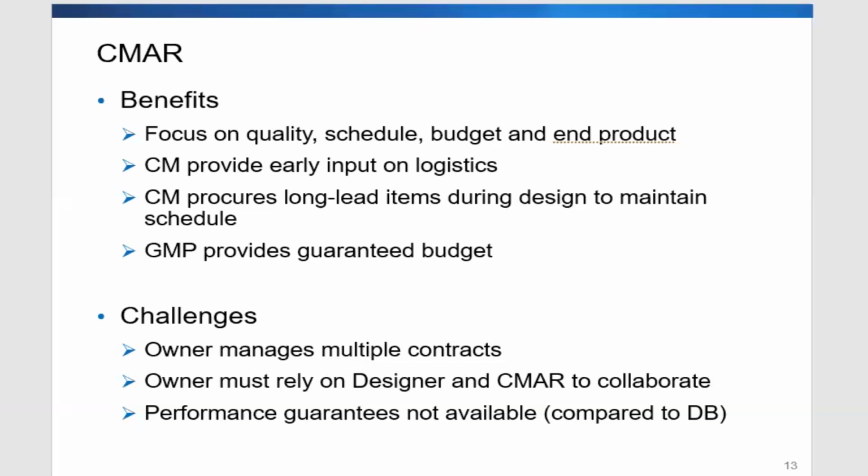And then also with this approach, since the contractor is involved early in the delivery of the project, the contractor provides input for the engineer to take into consideration during the design. There are various factors that the contractor can bring in, so that as we proceed to construction, any risk that could have been unforeseen circumstances would have been determined earlier on in the project by the collaboration between the designer and the contractor. And this also affords the contractor to procure what we call long lead items.